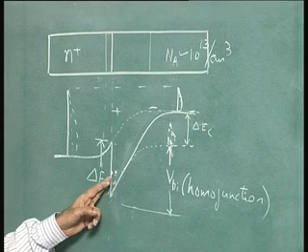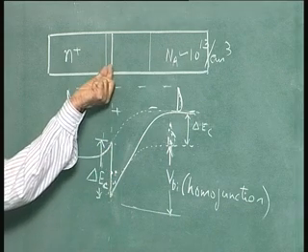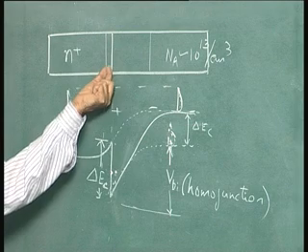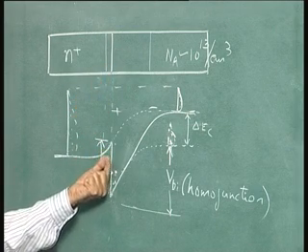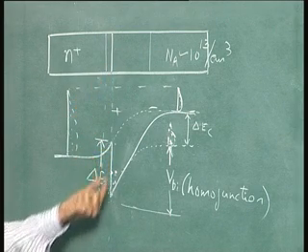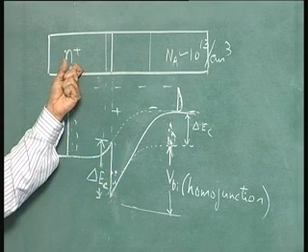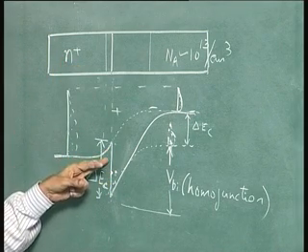So, what you do is you terminate a thin layer of 20 to 50 angstroms, usually 20 is the one that you put. Why we should restrict to 20 also will be clear when you see the transconductance of these devices. A thin layer you put which is not doped, but aluminum gallium arsenide. You need to put aluminum gallium arsenide only here to get this notch.